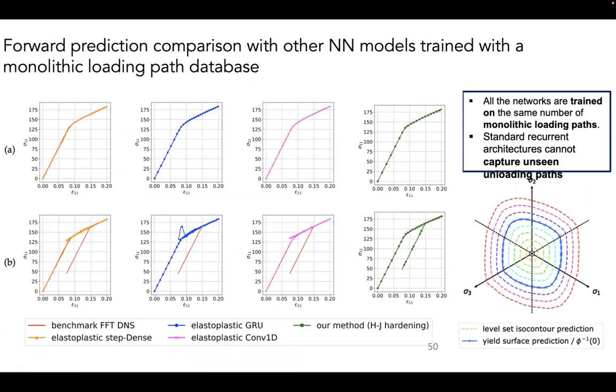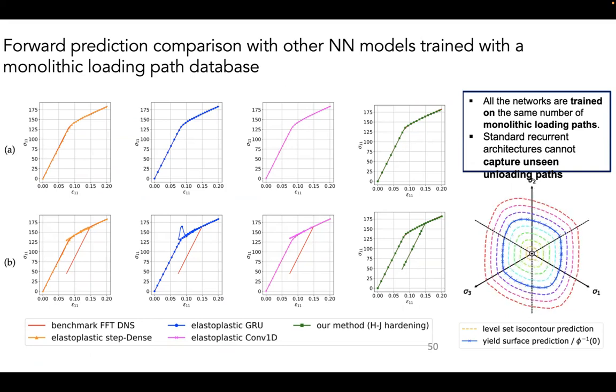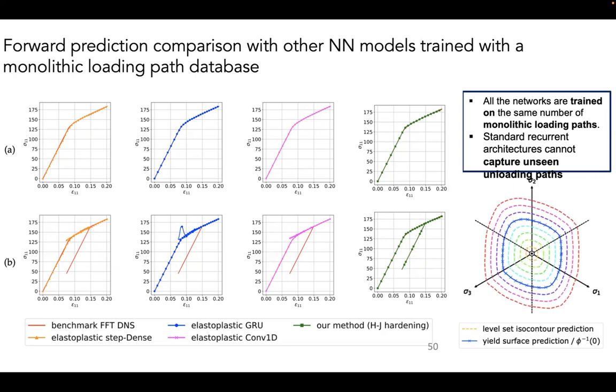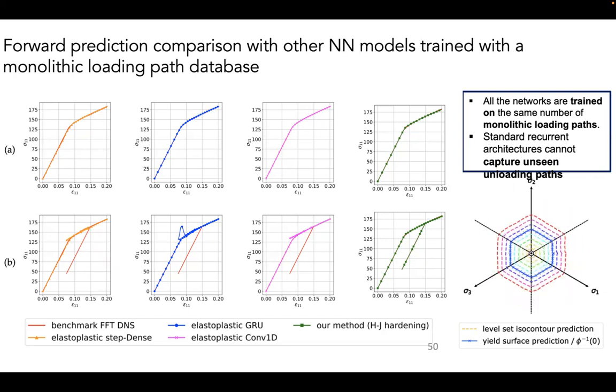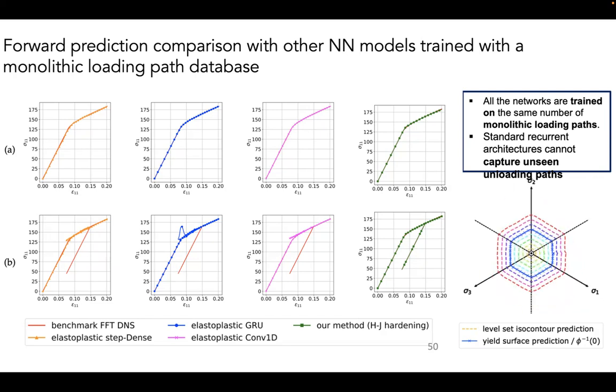And you can see the flexibility here. This is an actual polycrystal simulation. I have a polycrystal, I shear it in certain directions, and then I can break the symmetry of the yield surface from the data, and I don't need to explicitly write the constitutive law. There are also benefits to using that geometrical representation of the yield surface, in the sense that, for example, you can easily enforce the convexity.